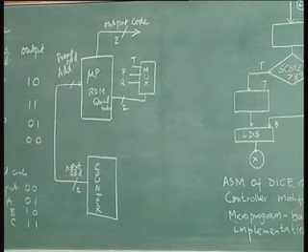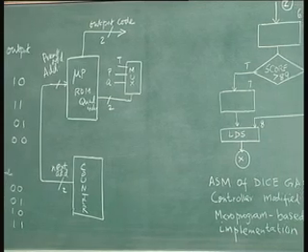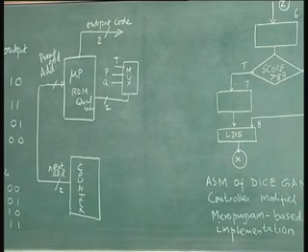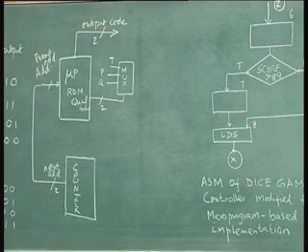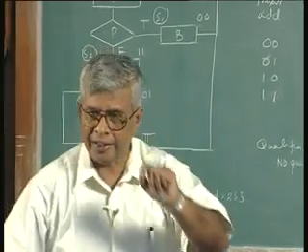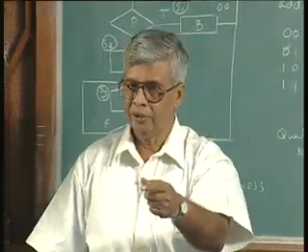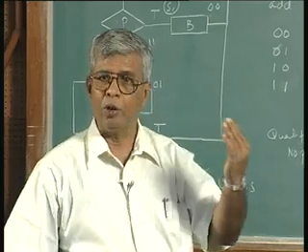This completes my design, and this counter will produce either a new value or an incremental value. If the next state is an incremental value of the present state variable, it has to add 1, or if it is a new value, it has to load a new value.